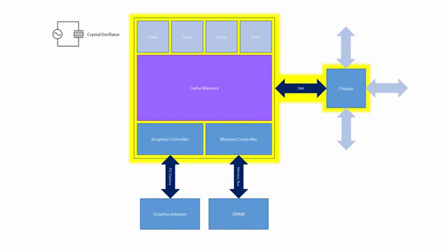If you buy a motherboard, it will most likely come with a chipset on it. The chipset dictates what type of CPU you can have, and because the memory controller is built into the CPU, this dictates the type of DRAM you can use. You can't just mix and match chipsets, CPUs, and DRAM. They have to be compatible with each other. Keep this in mind if you're planning to build or upgrade your own computer.